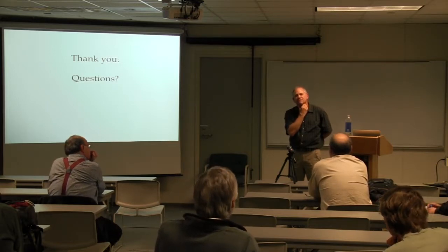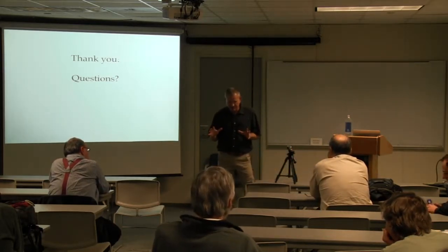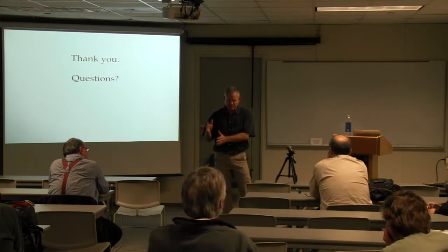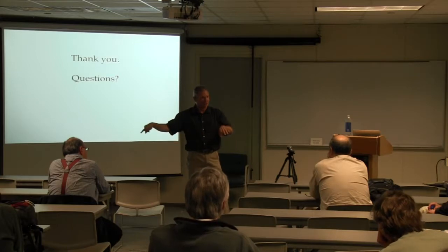Can you say what is different in any car today or in the future because of the stuff you're doing? What's different, you probably won't notice it. But when is your stuff in cars today? My stuff is not. But there are certain Mercedes-Benz and BMWs you can buy. So you have a crankshaft, you have the torque converter for an automatic transmission. For a manual transmission, and in lots of cars, there's something called a dual mass flywheel, which is nothing more than an inertia on a big spring. It can have large travel. It essentially softens up what's downstream.